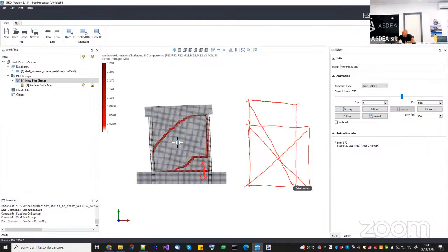So the two elements here will experience damage in tension. But the two diagonal elements are perfectly virgin. They do not have any problem, because in this case they are both in tension. So when I unload and reload on the other side, yes, I have damage here, but these two are perfectly undamaged. So now what is the real behavior? Let's say something in between.